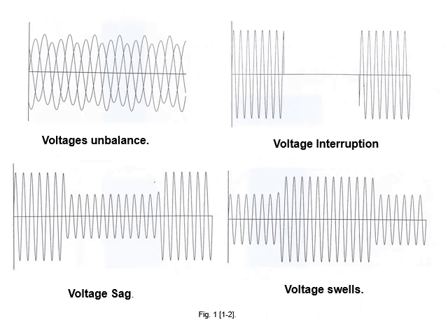See here, we discussed the balanced system. Balanced system means the maximum should be equal, and the difference between each phase is 120 degrees. But what happened here, you see the maximum values are different for the three phases. This is called unbalance. Or sometimes interruption, as you can see here, it gets off. Or voltage sag, the normal voltage is reduced here, as you can see. Or voltage swell, where it changes from the normal, as you can see here.